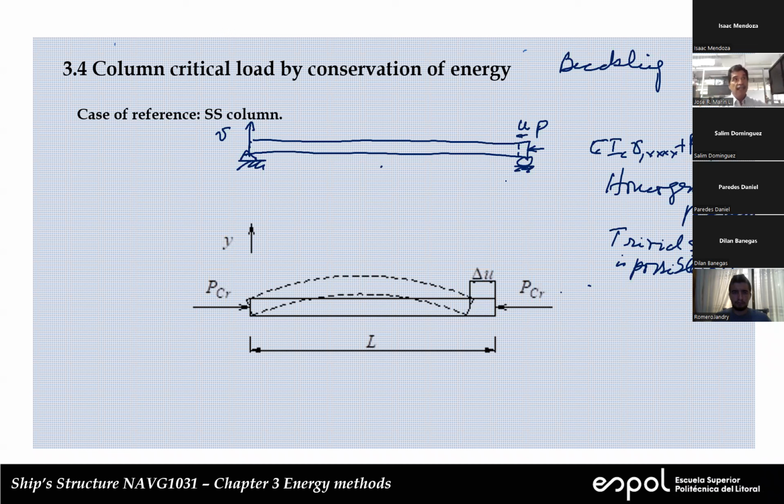Now, let's increase that force. We are going to increase this vector here. Because of this increment, the end is going to move like this. But again, we have not reached what we call the critical force, so we have no deflection again.